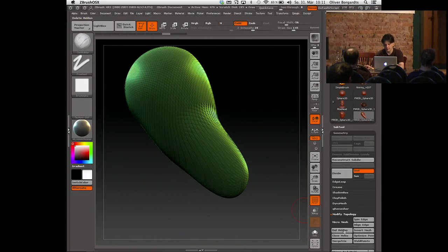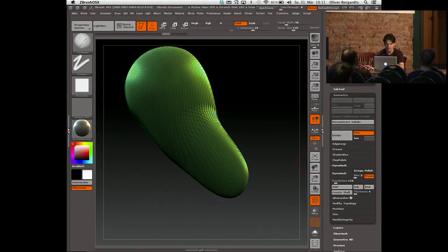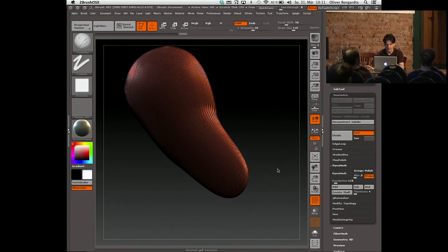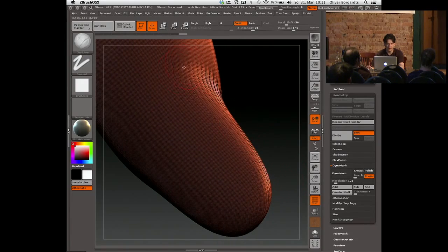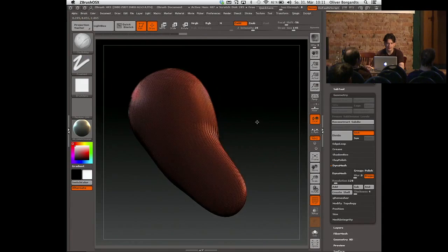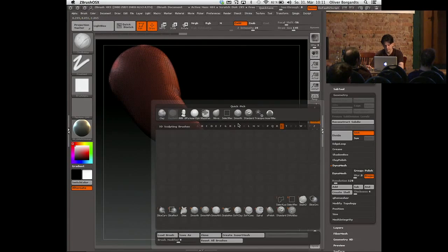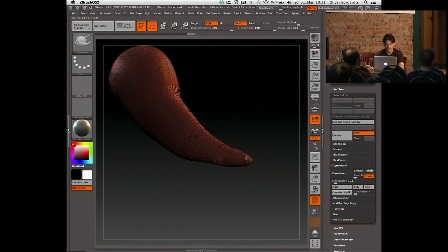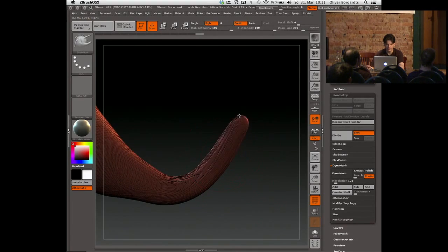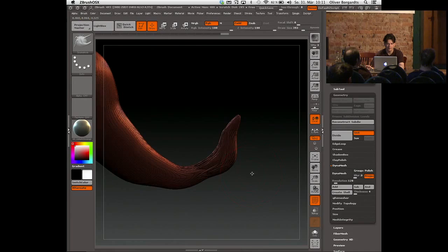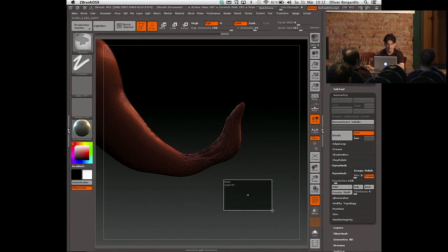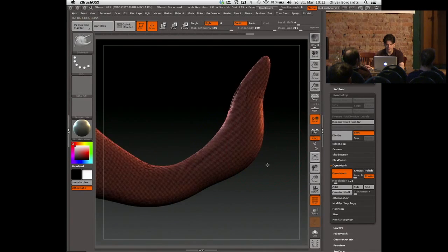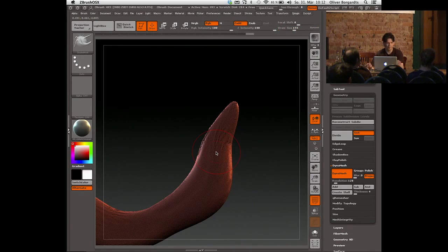And they included a technique or a tool called Dynamesh. If I activate this, my mesh will stay in the same shape, but will be internally remeshed. Say, if I pull some polygons out here, I lose resolution. I can smooth this, but I have no chance to apply greater details here. So I do a remesh, Dynamesh, and now I can work like clay, like I would apply a piece of clay onto my new part.